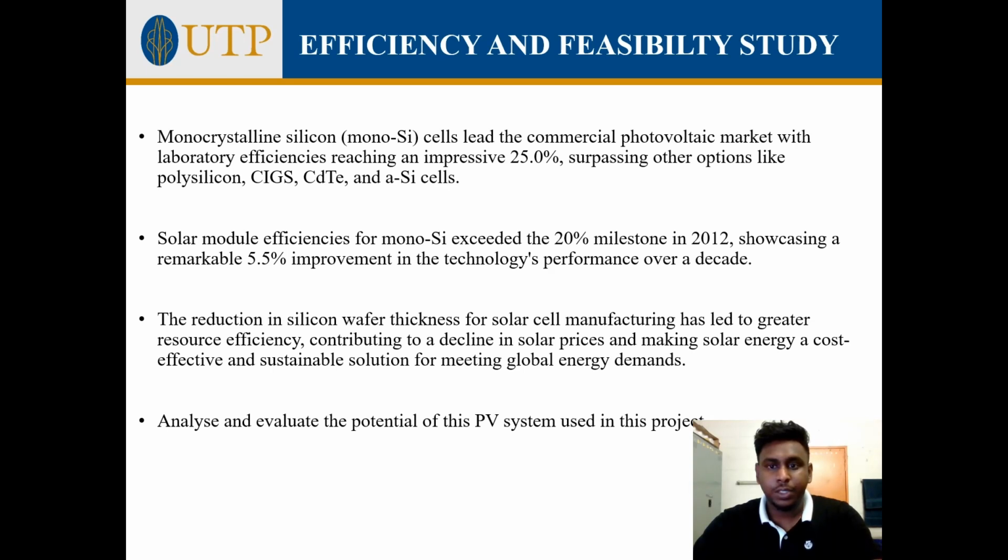Efficiency and feasibility study. Monocrystalline silicon cells lead the commercial photovoltaic market with laboratory efficiency reaching an impressive 25%, surpassing other options like polysilicon, CIGS, CdTe, and a-Si cells. Solar module efficiency for mono-Si exceeded the 20% milestone in 2012, showcasing a remarkable 5.5% improvement in the technology's performance